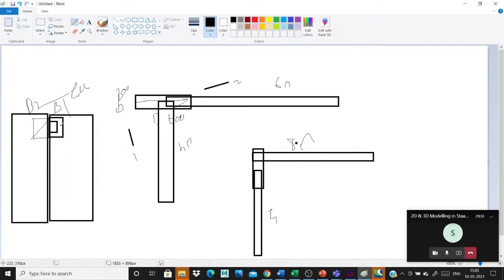The eccentric footing will be chosen for this type of boundary condition area. This is a main condition. You consider all these things before you design. That is an easy one. Okay, you go for the boundary condition. This is our boundary, this is another boundary, and this is a corner column. If you provide an isolated footing, automatically your pedestal will extend to another boundary. That is totally wrong. So for this corner column, I design an eccentric footing.